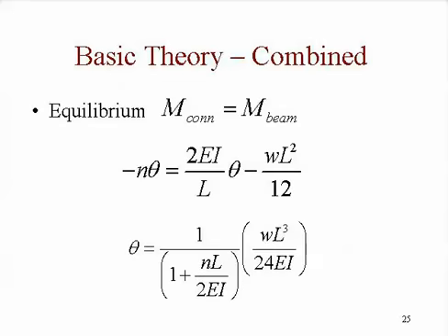So this is simple beam rotation. This ratio simply represents a multiplier to give you what reduced amount of rotation am I going to get. And if the spring stiffness approaches infinity, in other words, a vertical line, then of course the rotation goes to 0.